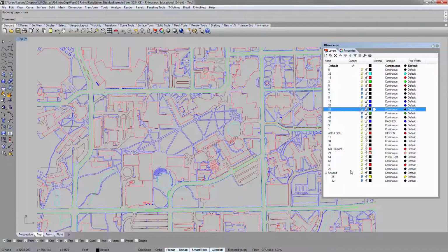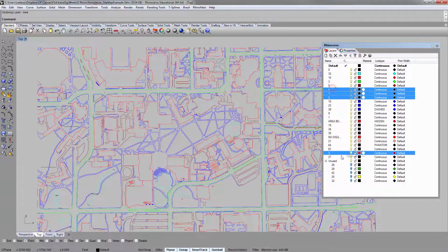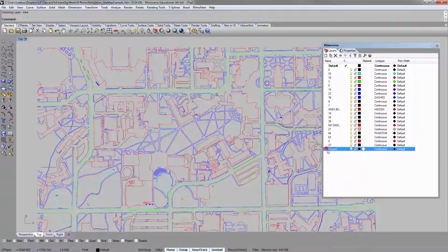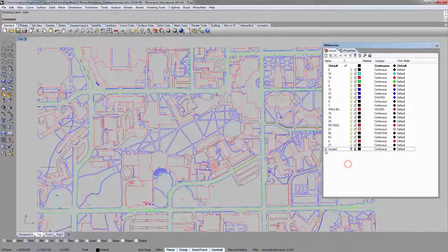So this is layer. By not clicking so close over there, but just staying on the name over here, and highlighting them together, holding down the shift key, right? So pick the first one, hold down the shift key, pick that one. So I'll just drag and drop them over here. Do the same with that. Okay, so that makes it easy for me to collapse and hide or even just lock the layers that I'm not going to use.